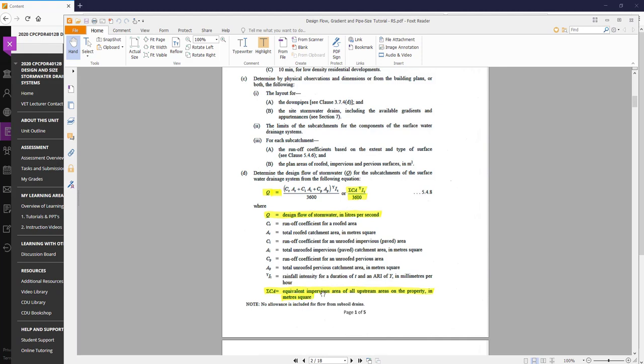Okay, impervious means it does not allow water to go into the ground, it all runs off, that's impervious, like a roof for instance. However, a grassed area may be pervious, which means it's able to accept some of the runoff into the ground. But for the sake of our exercise, being in Palmerston and being in a high rainfall tropical climate, we're not going to allow for that. We're just going to allow for it to all come off the property.